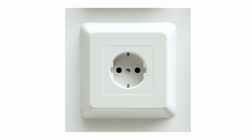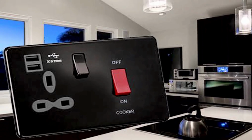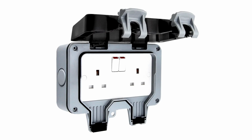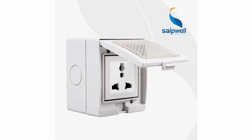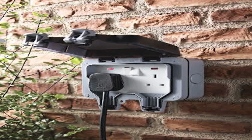We also have a power socket, which is used in places where motors can be found, such as the kitchen, bathrooms, etc. They are designed to handle a higher voltage. Thus, they are rated for 20 amps, 30 amps, etc. The 4th is the weatherproof socket, which is any of the 3 mentioned, but built with robust ingress protection to withstand water and dust. They are to be planned for corridors, outdoors, and kitchen while designing.